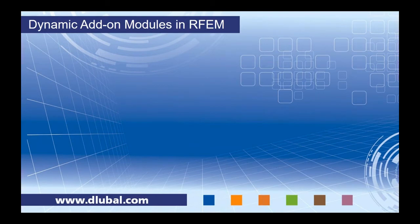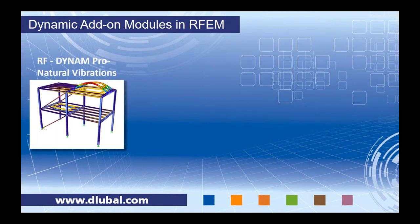So regarding the dynamic add-on modules in RFEM, RFEM is our main program. This is where we're going to fully model the structure. We can load it with various static loading and run an analysis. But anything to do with dynamics, whether that's natural vibration, forced vibrations, or seismic analysis, does require one of our dynamic add-on modules. So the first is RF-DYNAM Pro Natural Vibration. This is going to run an eigenvalue analysis that allows us to find the natural frequency and mode shapes of our structure.